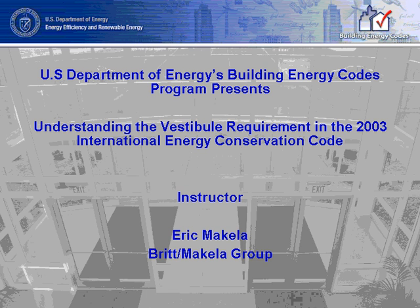Several questions have come up from a vestibule requirement standpoint as states start to adopt this. Two states, New York and Texas, have had this since approximately 2001. Since its adoption, there have been several issues from designers and jurisdictions on how to enforce the code requirement because, unfortunately, within the IECC, the requirement is not as clear as it should be. Several of the questions that have come up entail which entrance doors must have a vestibule, when is a space, because it's not entirely clear within the code, and how can I exempt my project, which is a very popular one.